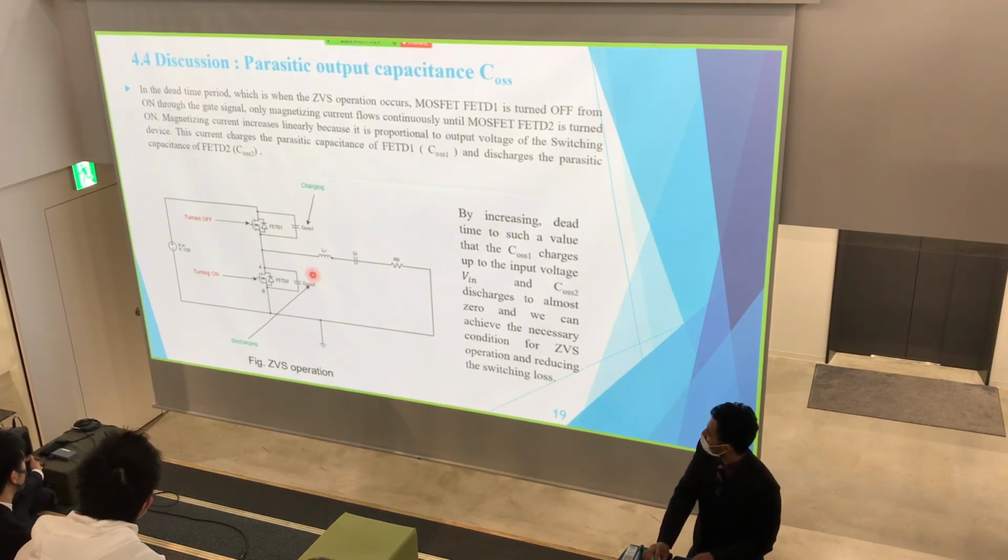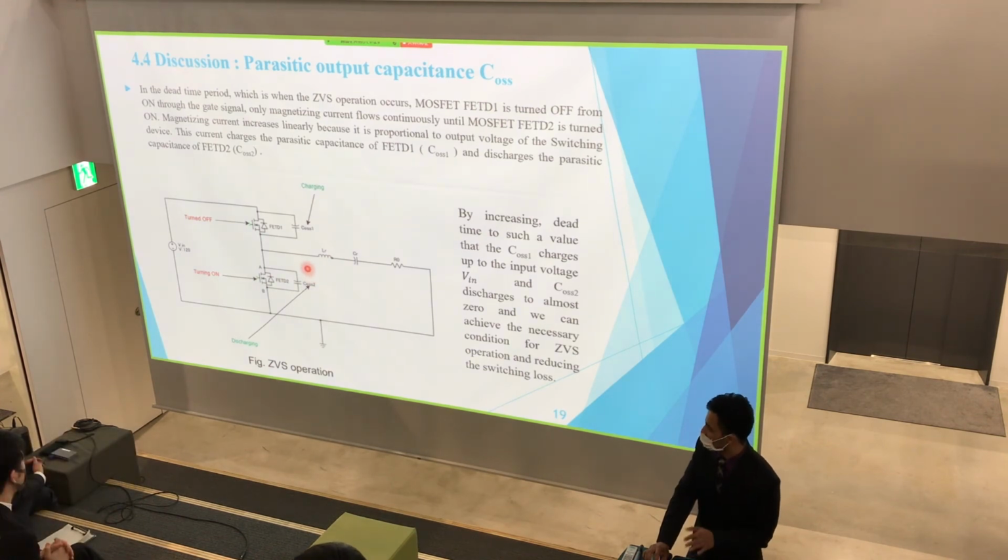We get the peak value. And for a reliable dead time, and to optimize it with the inductiveness of this resonant tank, we should calculate the optimized dead time, and then we can get a higher amplitude of current across this resonant tank.